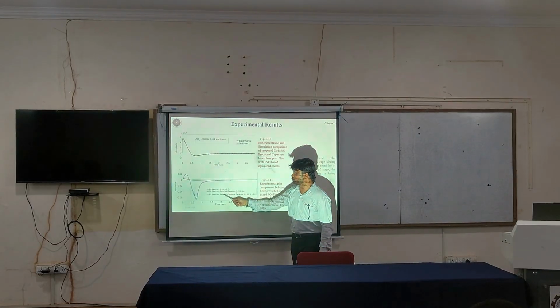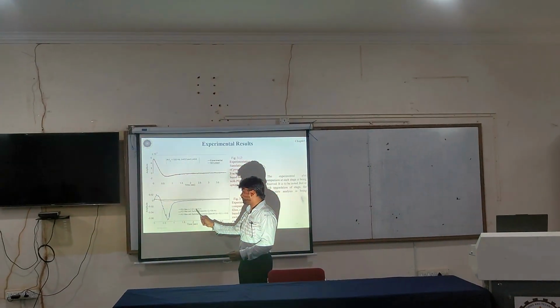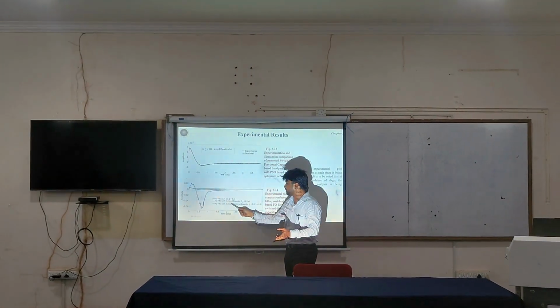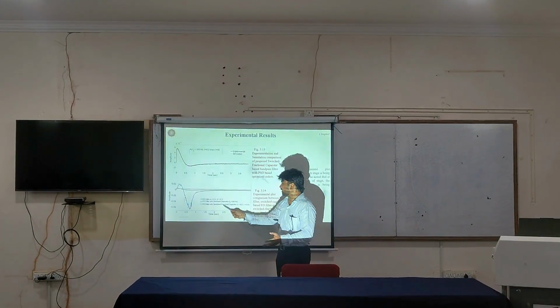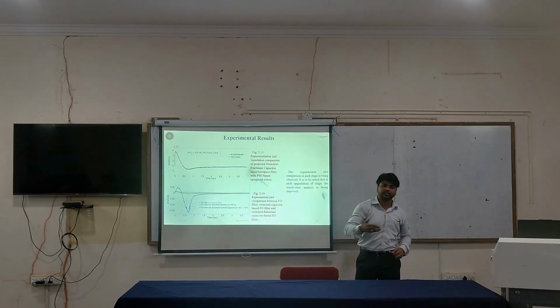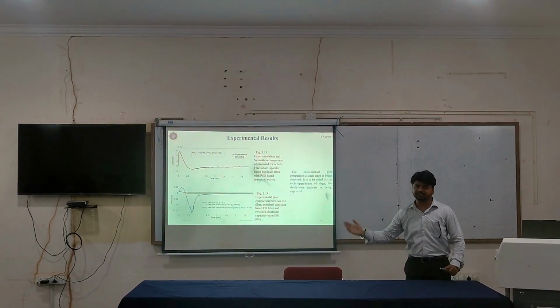And this graph finally shows the fractional order filter at alpha equal to 0.3 and 0.7 with the two resistors. Then those resistors were replaced by switched capacitors. Then those switched capacitors were replaced by switched fractional capacitors. In this way, the performance goes on improving. That is, the settling time, the rise time, and the peak overshoot slowly decrease.